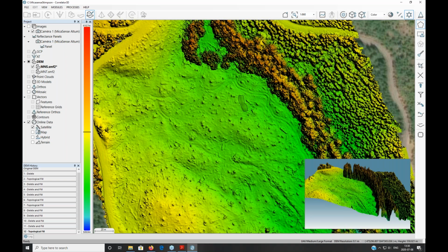One thing, if you want to calibrate your reflectance, is that before generating the ortho photos, you can import your reflectance panel. Your reflectance panel can be imported as soon as your project is created, but it needs to be done before doing the orthorectification. So you can do the AT, the DEM, and then import your calibration panel, or you can create your project, import your calibration panel, and then perform all your steps. At this point, it's not going to have any impact on the processing. It's only at the ortho photos creation that the DLS sensor and the calibration panel will be taken into account for the remainder of the processing.